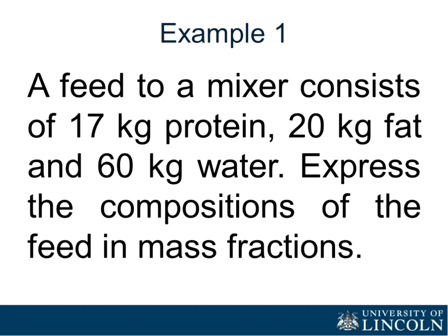Now, a feed to a mixer consists of 17 kilogram protein, 20 kilogram fat, and 60 kilogram water. Express the composition of the feed in mass fraction. So a feed to a mixing equipment, we have 17 kilogram of protein, 20 kilogram of fat, 60 kilogram of water. Now, we want to express the composition in mass fraction. Let's look at how we're going to do that.